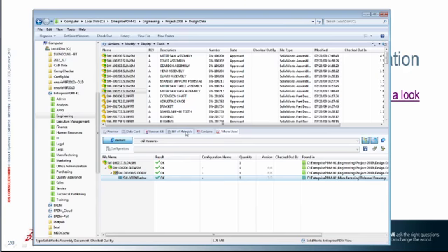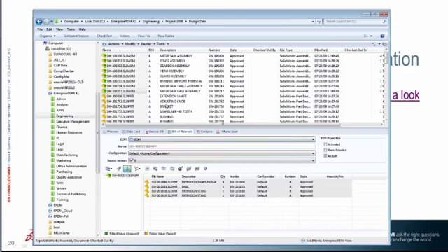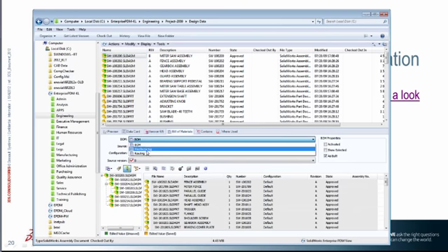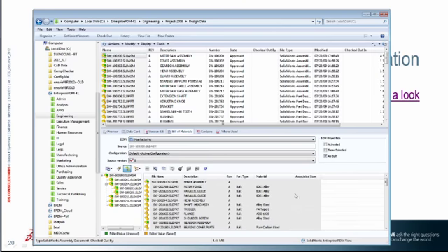All right, so let's get back to the Bill of Material tab, and we'll take a look at this assembly. Right up top here, let me go to a larger assembly to give us a little bit more to look at. Up at the top here, I have a selection where I can pick different BOM templates. So my standard one is just my BOM template, but I also have a manufacturing template that will list different data in my BOM view.